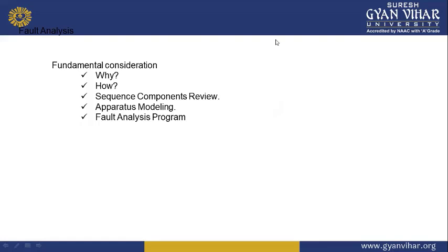So far, we have seen the steady state behavior of power system under normal operating conditions and its dynamic behavior under small scale perturbations. Now, this lecture is totally devoted to the abnormal system behavior under conditions of symmetrical short circuits. Such conditions are caused in the system accidentally through insulation failure of equipment or flashover of lines initiated by a lightning stroke or through accidental faulty operations.